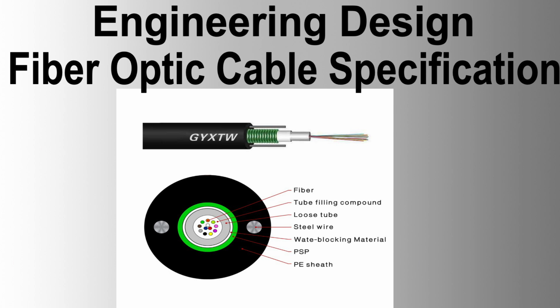Printer, preferably internal, capable of printing data traces within 30 seconds or less. Machine settings include index, range, wavelength, average time, pulse width, and scale settings. Test results should include loss, distance, reflectance, date, and time. Compare trace feature: ability to recall 2 historical traces from a diskette, display them simultaneously for analysis, and compute display differences. Must perform a 2-point loss measurement test for any 2 particular fibers in comparison analysis.